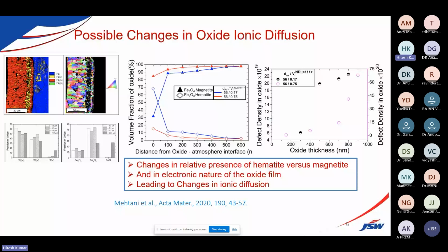But EBSD of a powder is quite difficult, because you are tilting it at 70 degrees and placing the powder for a longer time. In powder the heterogeneity will be there. And the question is, what is the size of your powder? Whether 1 micron or 2 micron is also going to have an impact, no?